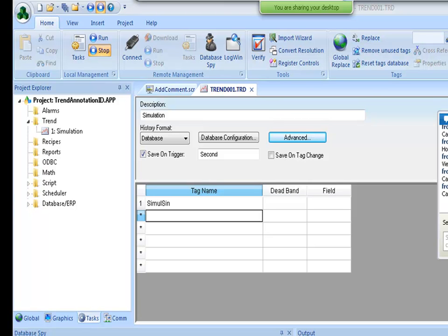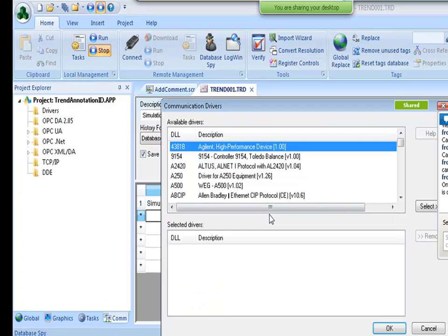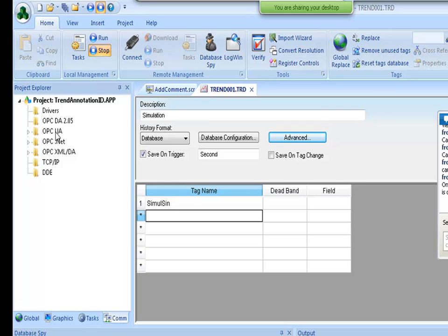Can we change the sampling rate at which the data is collected? Yes, you can. Remember that with data collection you have 3 phases. You have data collection, you have data saving into the proprietary files or databases, and you have data presentation on the trend control. The data collection is controlled by the communication driver that is reading data, or the OPC client module that is saving data. So you have controls there to define how fast you are acquiring data, and there is always a physical limit from the network and from the computer power that you're using. But you can configure as much as possible the sampling rate to read data from the controllers using the driver or the OPC interface. Then in the trend worksheet, you define how often you want to save those values